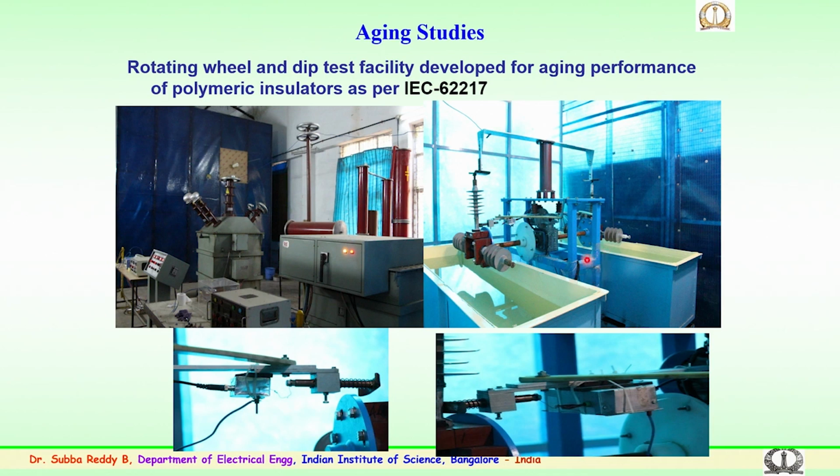This was the idea. The fabrication has been carried out, and important is, during the high voltage contact, this is a dipping period where the insulator dips, and this is a dripping period. Next comes the high voltage contact and further cooling or the resting period. During this contact of the high voltage, the important thing is to measure the leakage current.